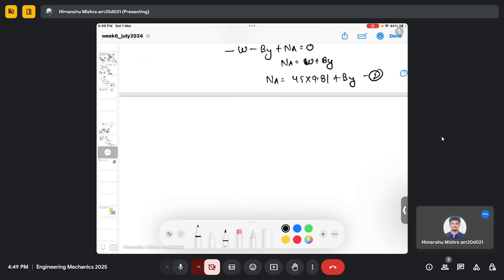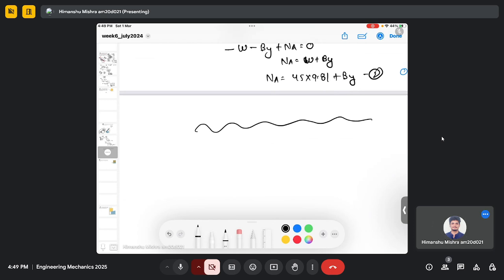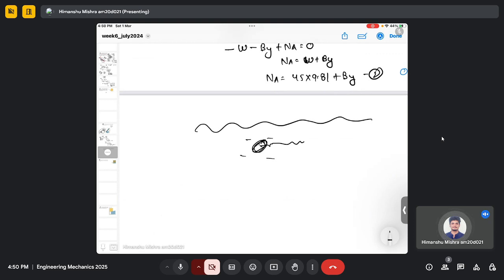in the oceanic flows. So let's say you have surface waves or ocean, and you have a microplastic which is floating at the surface of the ocean. Researchers now are very interested in this trajectory, how this particle moves. In that case, you can actually use Euler equations, where you identify this particle as a rigid body and you have a flow field. From the Euler equation, you can describe its rotational motion, how it's rotating. So from the kinematics or the kinetics part, you can describe its rotation or maybe its translation motion.